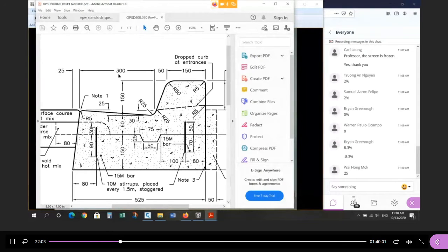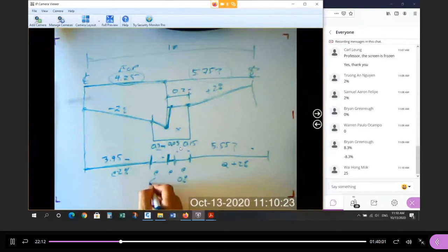And it's negative, right? From center to the edge, it's going downhill. So we're looking at a slope of negative 8.33333. It goes on forever, 8.33%. So this is going to be negative 8.33. A horizontal distance of 0.3 with a slope of negative 8.33.